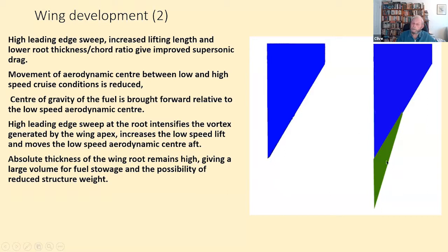The other thing it does is that you can fill that up with fuel. So you bring the center of gravity of the fuel forward relative to the low speed aerodynamic center, which enables you to get stability at low speed. The fact that it's a high leading edge sweep intensifies the vortex development and increases the low speed lift, and it actually helps to move the aerodynamic center aft as well. And as I said, the thickness at the root remains high, so you've increased the fuel volume, which is good, and you've also got a chance to reduce the structure weight.